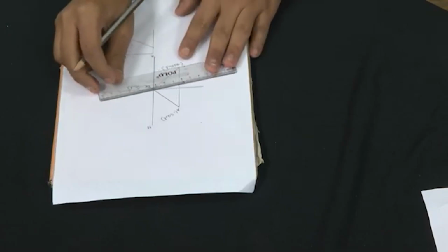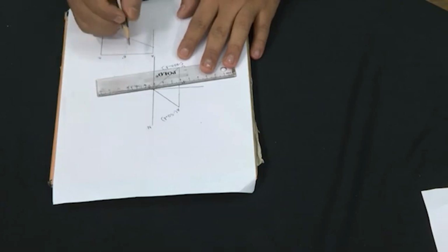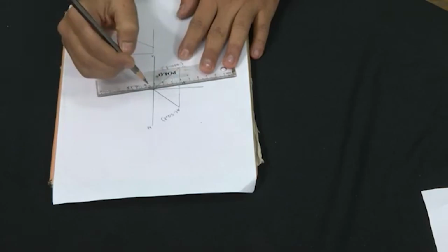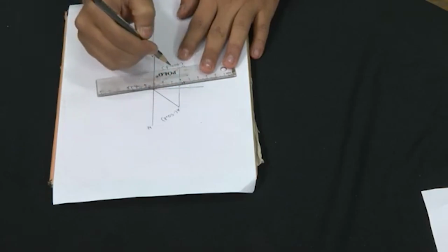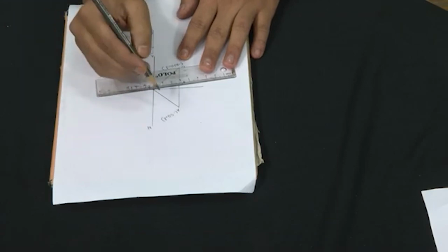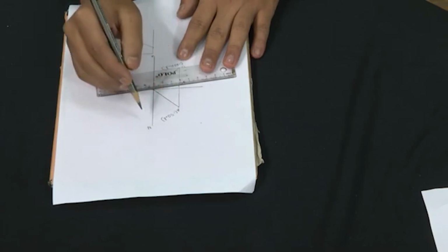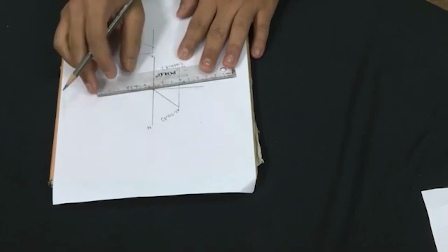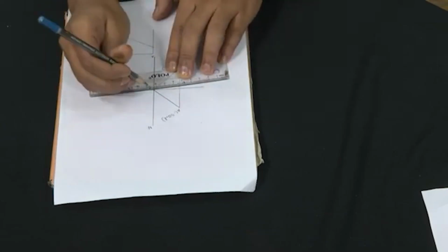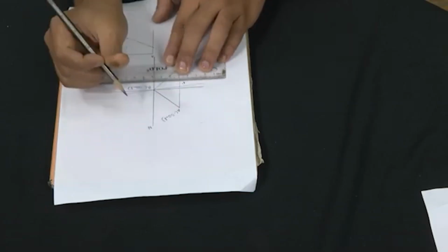minus 130 meter strike line, and then if I construct a parallel line, any parallel line to the corresponding 130 meter strike line from the point A or from the point C, we will get another strike line. From point A if we construct, we will get a strike line of minus 50 meters. If from point C we construct, we will get a strike line of minus 220 meters. First I construct the minus 130 meter strike line, which is this.